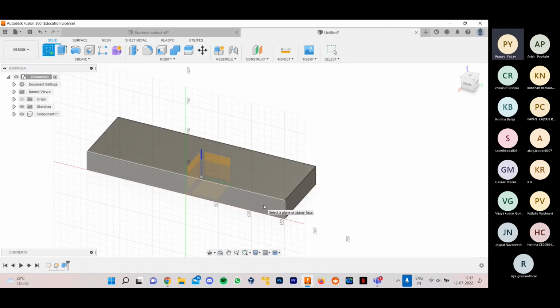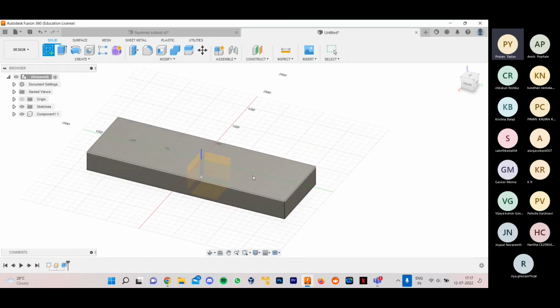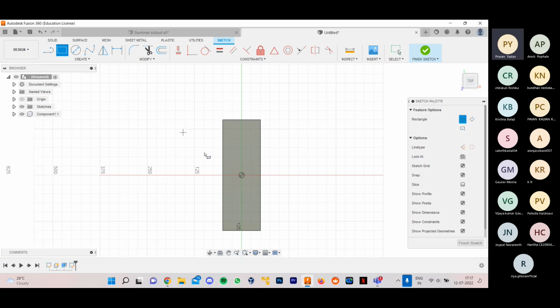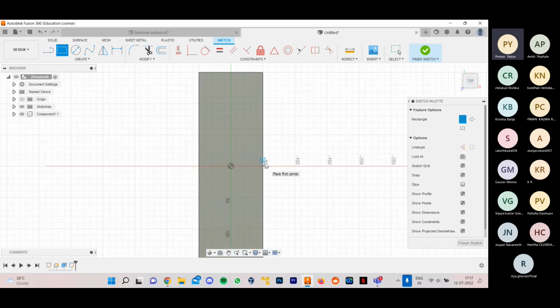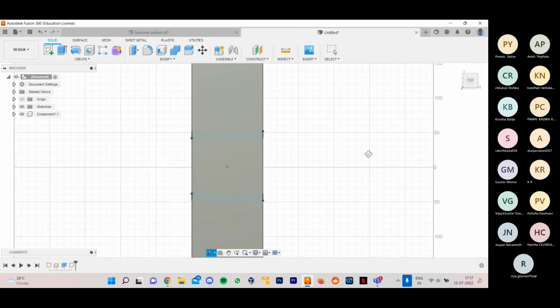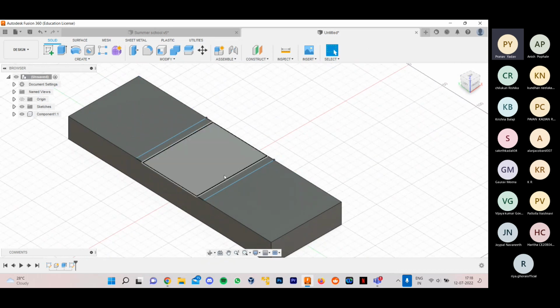So I can create here, I can create here. I want it here now because I want to have those two plates. So I'll be clicking on this plane of that object. I want these two plates. By logic, they'll be created by creating two small rectangles. I'll be creating a small rectangle here and symmetrically here, which is I think 10 by 100. Each rectangle is 10 by 100. I'll finish the sketch. Also, you can see that the plane I selected is where the sketches are at.